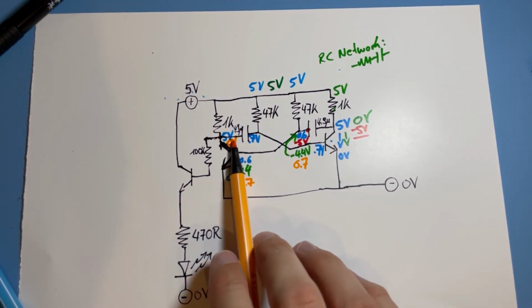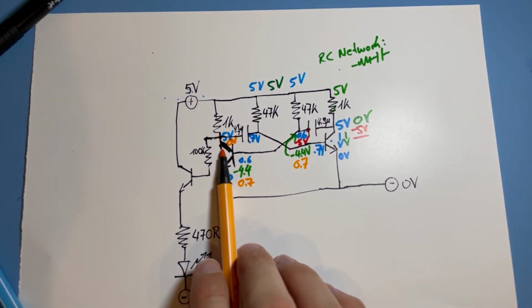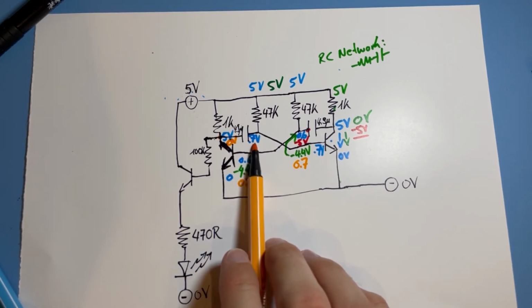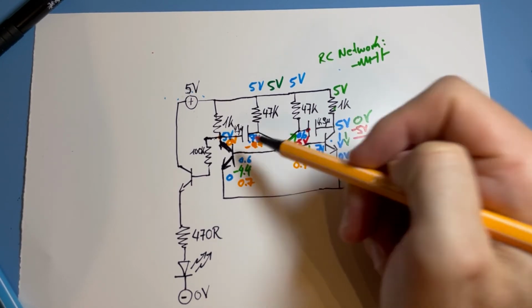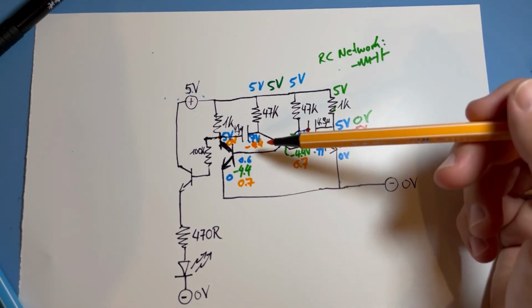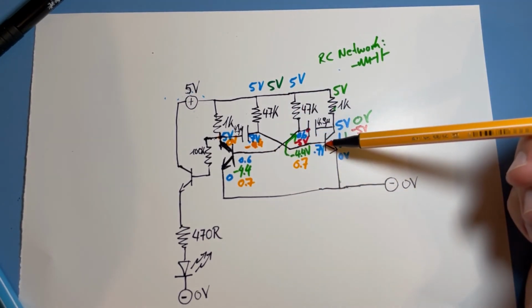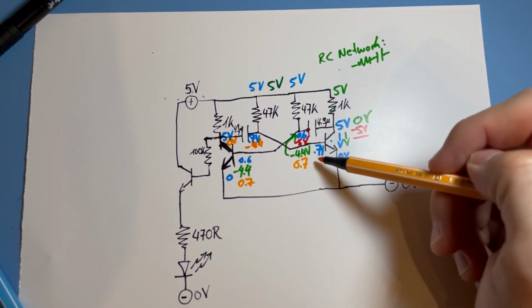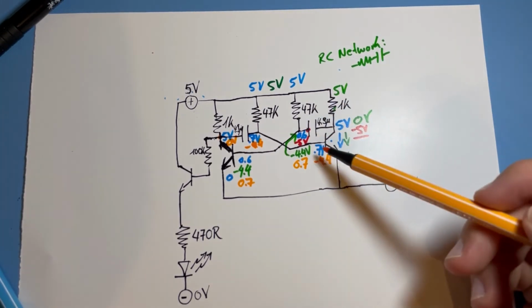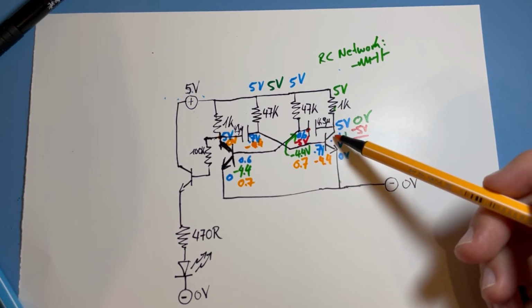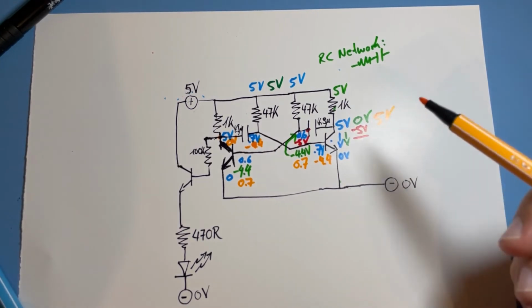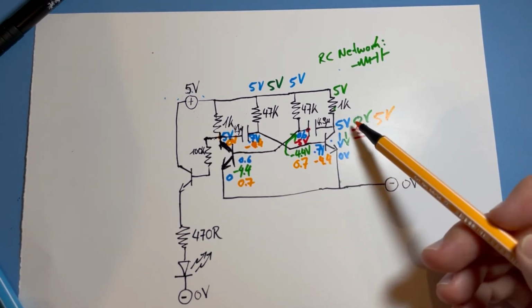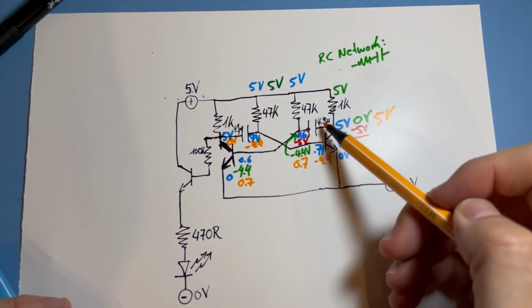And then 0 volt, and the current goes through the negative terminal through here. Meaning, if we have a drop from 5 volt to 0 volt here, this means again 5 volt down. Then this 0.7 volt that was here before now drops to minus 4.4 volt. Minus 4.4. I hope you can read it. And then the base here, which is at minus 4.4, this transistor stops conducting, and you get immediately again 5 volt here, where you had before 0 volts.